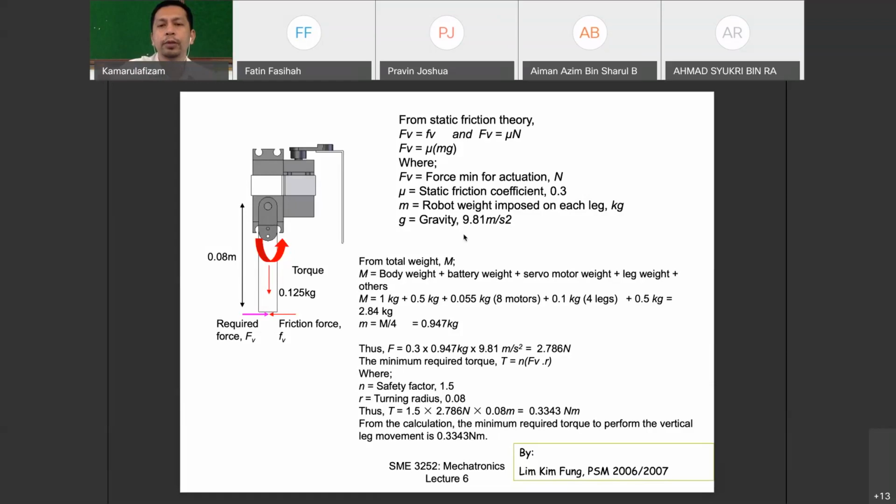Alright, so your gearbox must be designed to handle motion or mechanical energy, at least the minimum that you can receive. That means if you get torque from the engine, I'm speaking in the context of a car, if the engine is producing, for example, 300 Newton meter of torque, the gearbox must be able to handle at least 300 Newton meter of torque to transfer to the driving mechanism, the tire or whatever. So the gearbox must be able to withstand that.